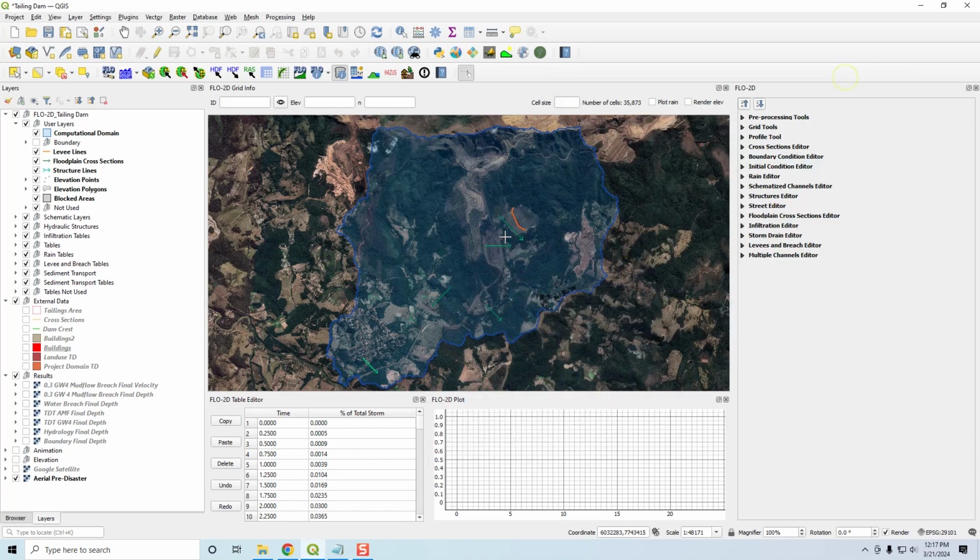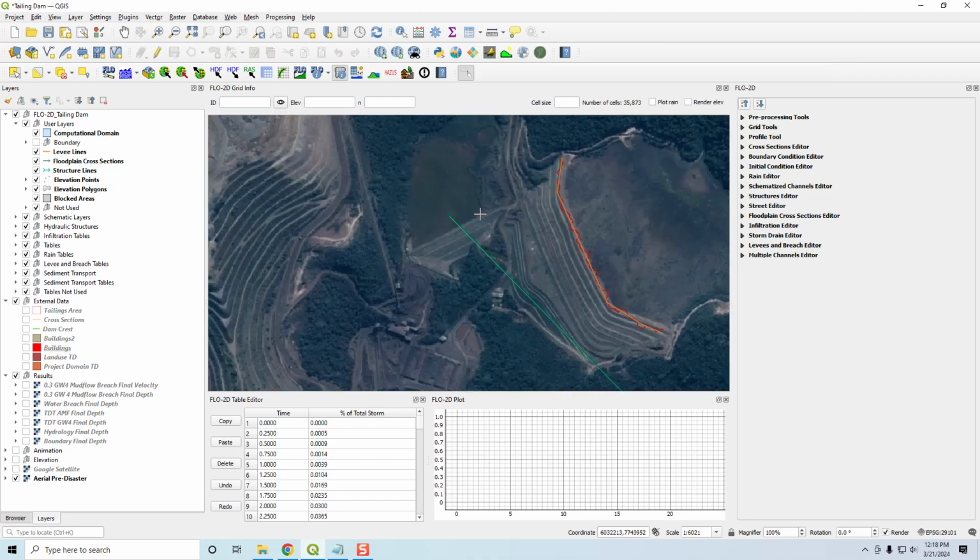For example, this one is a static stack failure, but this one over here is more like a quintessential tailings dam where it has a water surface on top all the time, and it's probably a slurry, and so there's definitely a difference in the final concentration of the mud or the tailings that are in here, and different parameters that you would model that with.